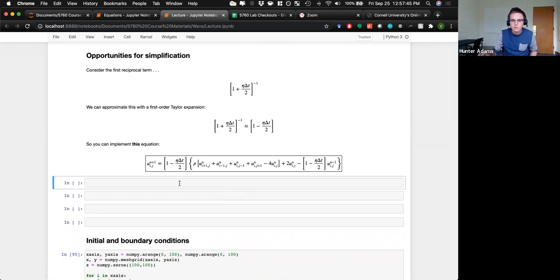And the implementation itself, like we talked about last time, right? Everything in these brackets is adds, so that's easy. This is a multiply by 4, so that's just a shift. Multiply by 2, that's just a shift. With strategic choice of eta, you can make this first term and this term a power of 2. So you could also make these shifts.